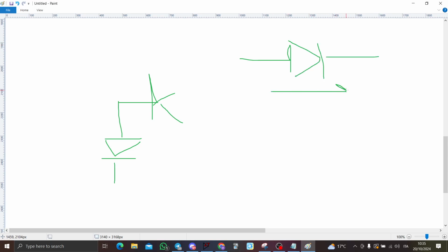So what happens if you put the diode like this? Well, let's reason all together. You know that the diode is a device that makes the current pass in one direction if the voltage across it is higher than the potential barrier. So this is the anode and this is the cathode. The drop voltage VAK is 0.7, and the characteristic of the diode is like this. With the 0.7 drop, and if you want to implement the linearity, it is like this, as you remember.